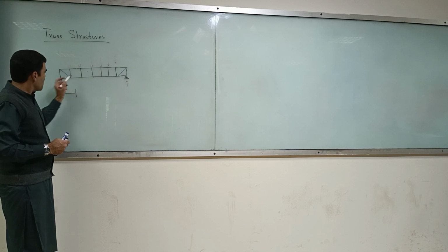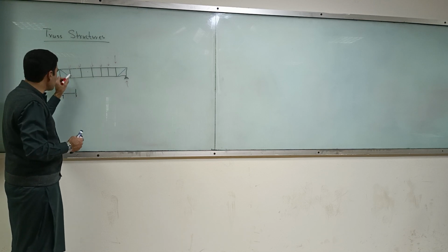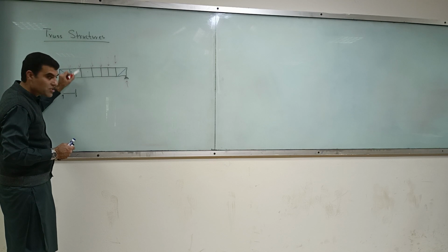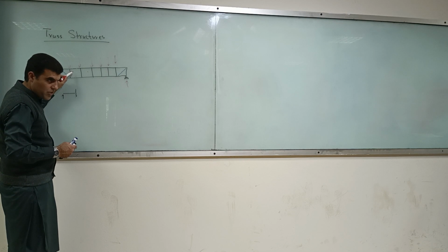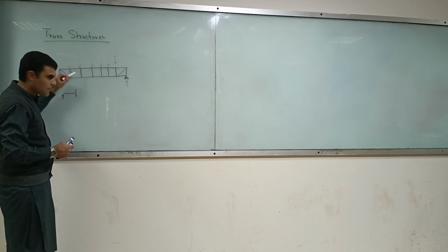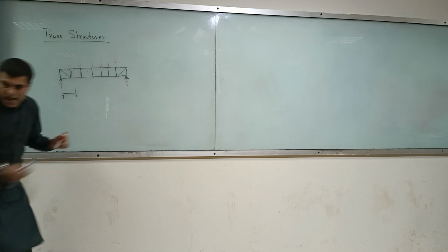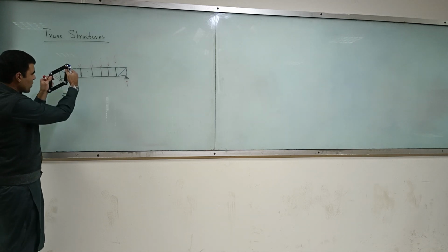That is this minus that, which direction is upward, okay? And over here, slightly before this vertical member, if this is upward, summation of Fy must be equal to 0. So this must be downward. So this is up. So I will take my link, apply load up, and this one down.